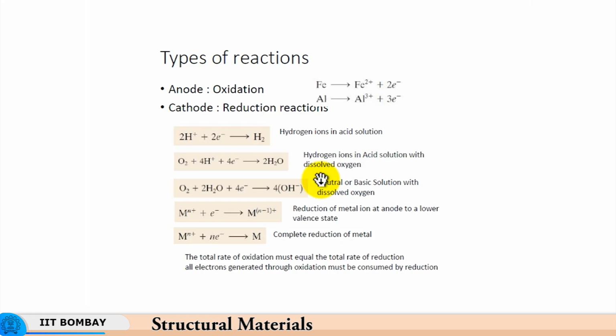So, basically the electrochemical series which we have seen helps us in understanding the possible sequence of these elements going into solution when an alloy having several of these elements is present in a given solution. Plus there can be different phases which impart a different degree of anodic nature. For example, pearlite would be more anodic as compared to ferrite, and so pearlite would get attacked first as compared to the ferrite.